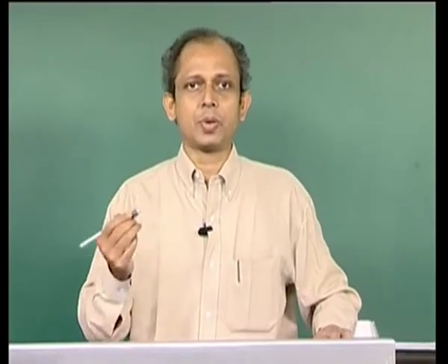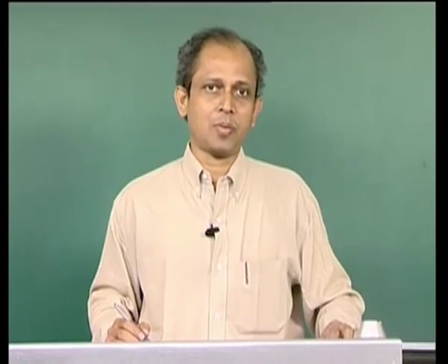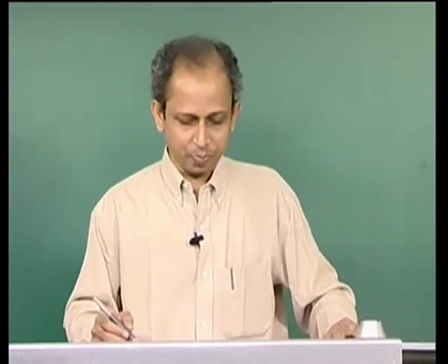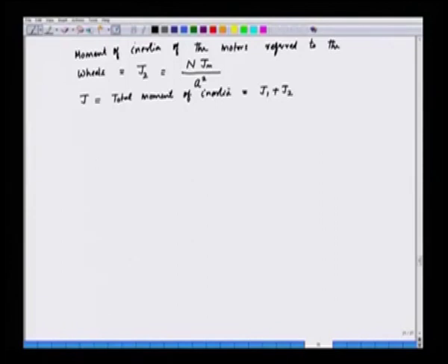So we have linear acceleration, and that has to be converted into angular acceleration. So if the radius of the wheel is r meters, we can convert alpha into angular acceleration as follows. So what is the linear acceleration? The linear acceleration is equal to alpha in kilometer per hour per second. So we have to convert into meter per second square, into 1000 divided by 3600, that is meter per second square.